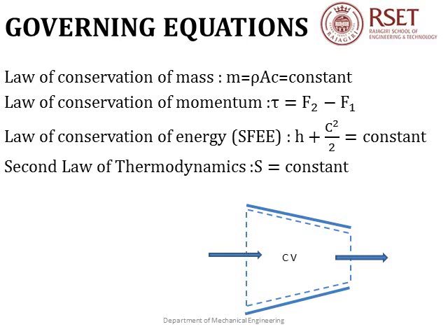For the law of conservation of energy, or the energy equation, we start from the steady flow energy equation, which is the simplified form of the energy equation for a steady one-dimensional flow. Here, for an isentropic flow, the work transfer and heat transfer terms reduce to zero.